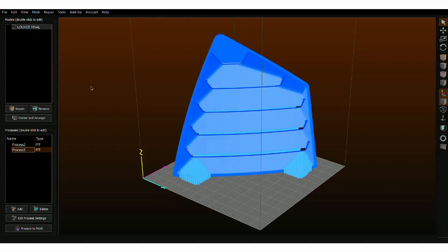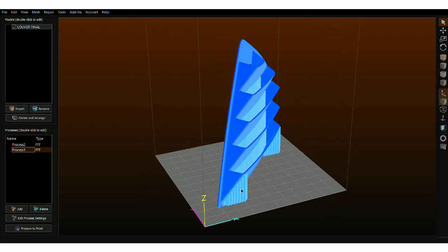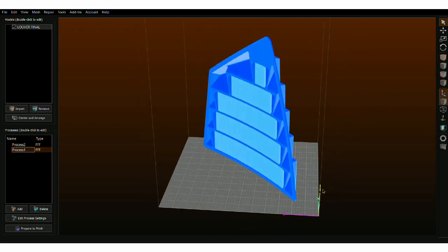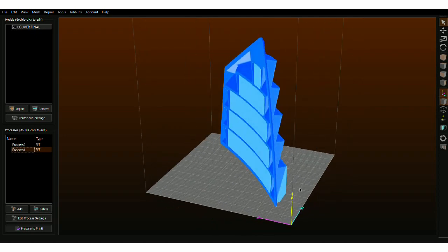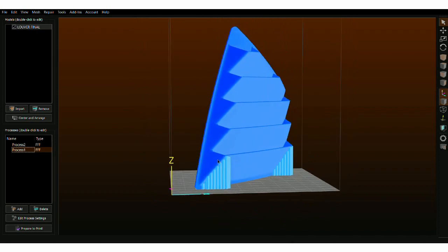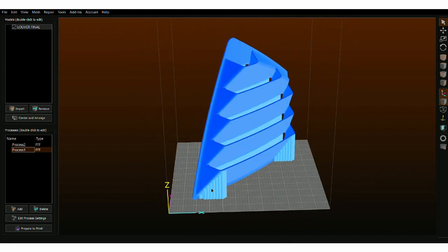Once finished with the model in Fusion 360, I had to create an STL file to export and load the model into the Simplify 3D software. You'll notice that the slicer simulation that I show is from a revised louver that I created to have the actual contour of the window frame with only one flat edge that I use for my table base.